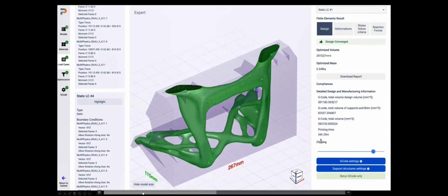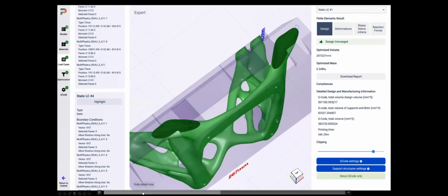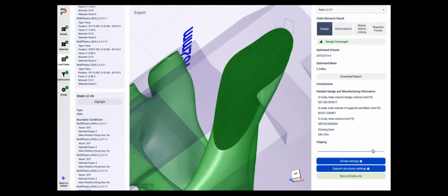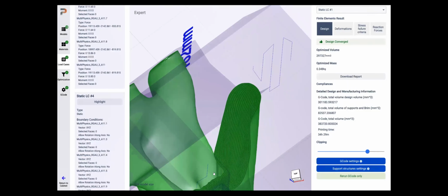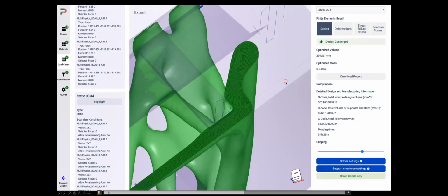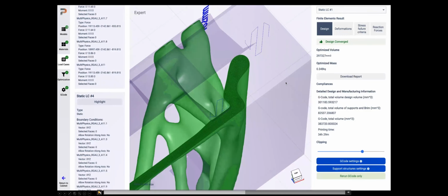So we have a full freedom here of orienting and optimizing material placement, which is I would say huge, right? Because current traditional composites manufacturing is really limited to a given prepreg orientation. So this is a big advantage. I hope it answers the question correctly.